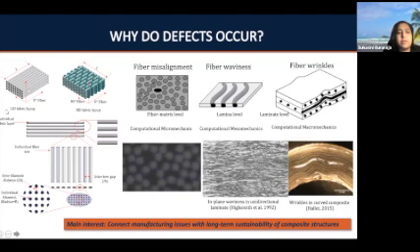This is just an example of a BD fabric, a bidirectional fabric, which is used quite extensively for making different components. If you look at it carefully, these are essentially comprised of fibers, and the fibers could be carbon, glass, Kevlar, what have you. A collection of these fibers tends to make a toe. Each fiber, as you know, has length scales in the range of tens of microns. As you keep going up the length scale, the complexity of the material also increases. A collection of fibers becomes the toes, a collection of toes becomes a ply, and the plies are laid on top of each other in different configurations, and you end up getting BD fabric. And then of course you have the complexity which comes into an actual component.